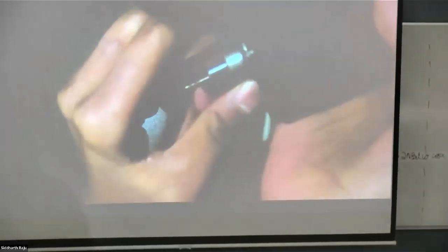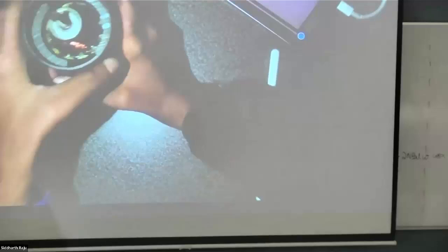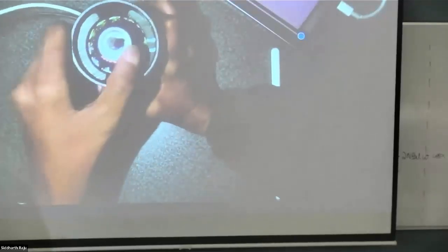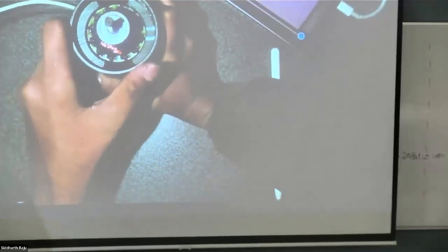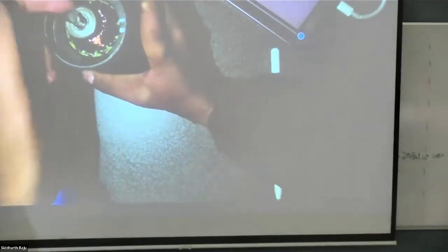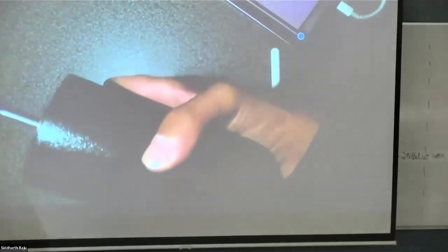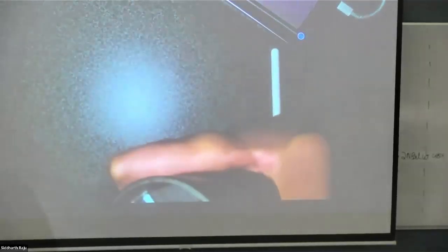So this bearing is very critical because the rotor can't float in air. There is no levitation mechanism, right? If you leave it to itself, the rotor will go and attach to one of the two magnets because it's an iron structure. The air gap is just 1.5 mm in length, so visually, it's not even perceptible. So the manufacturing tolerances are very, very tight on these. You will have a faceplate on which this bearing rests so that the rotor can rotate and still have mechanical support to keep it, I shouldn't use the word levitated, but levitated in the air, all right?